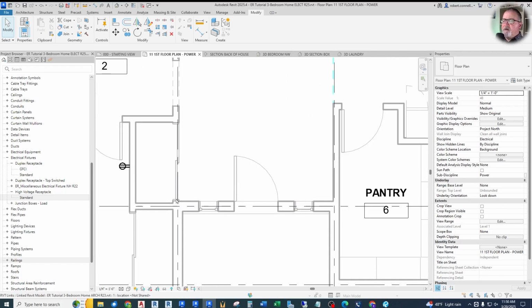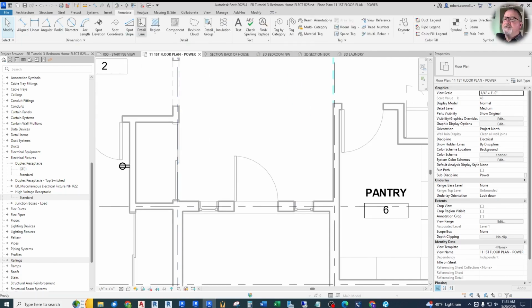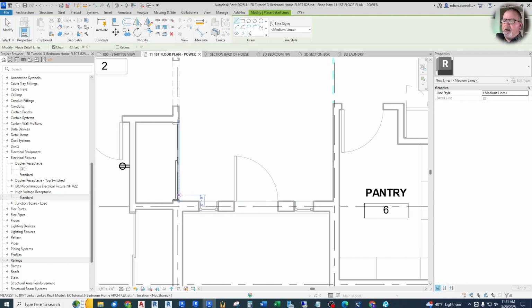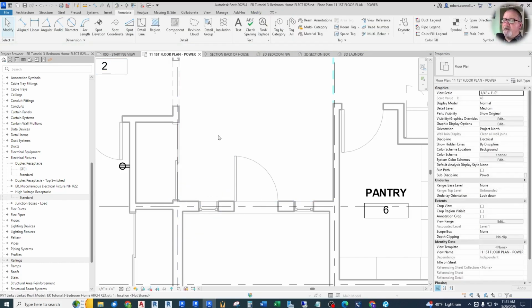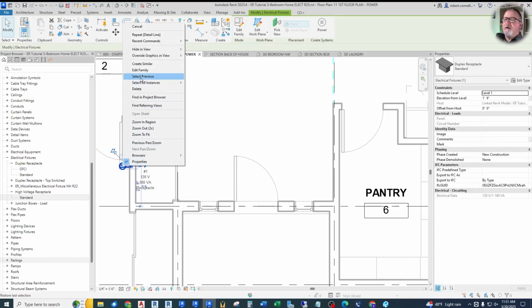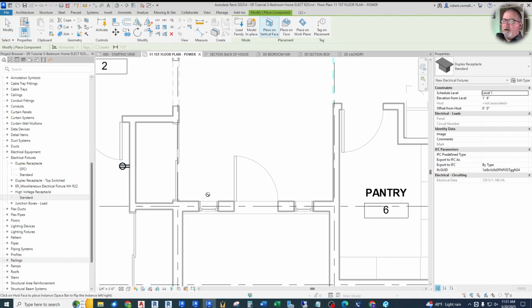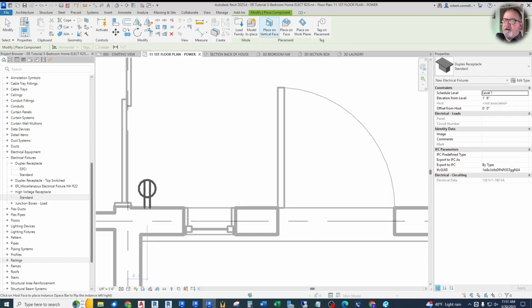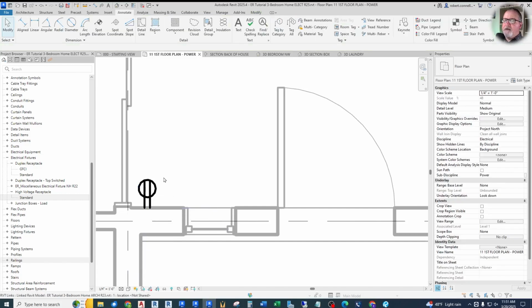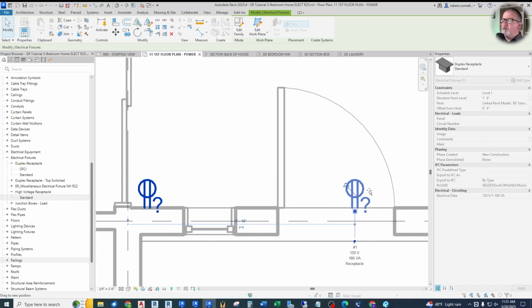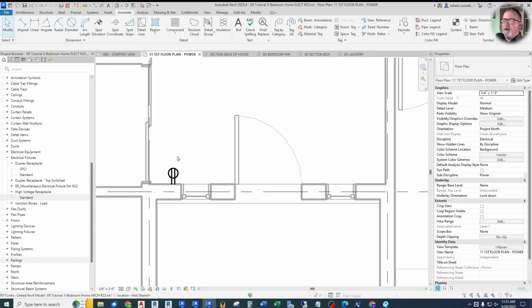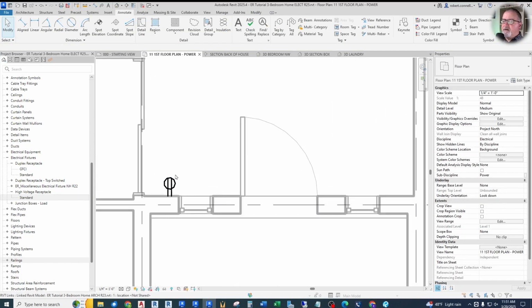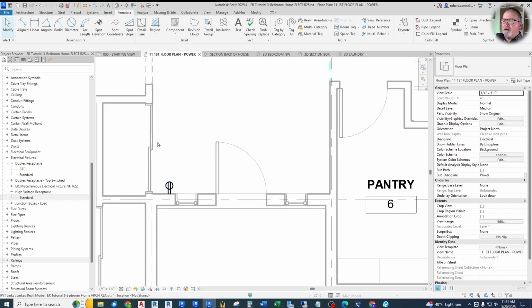So is this piece of wall wider than 2 feet? We can double check with our measurement system and see 3 foot. Yeah, it's almost 4 feet wide. So we need a receptacle. So let's go ahead and create similar from here. Now again, are these windows too high? And now see, as you get here, it wants to jump around. So what you can do is place this on a good piece of wall here, escape out, and then you can drag this around along this wall. It'll even go to the other side of the door if I want. So I'm going to put this here, and I'm going to stay just a little shy of that window. If someone sets a little table with a lamp, they have a way to do this without stretching across.